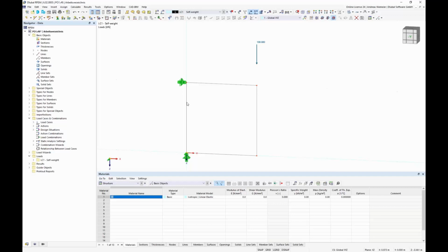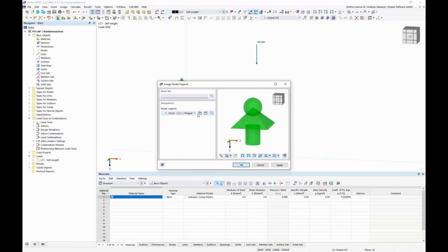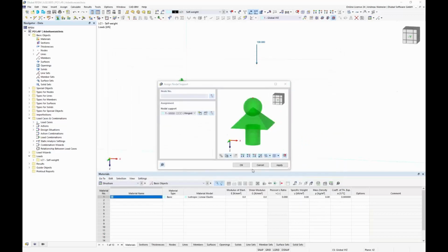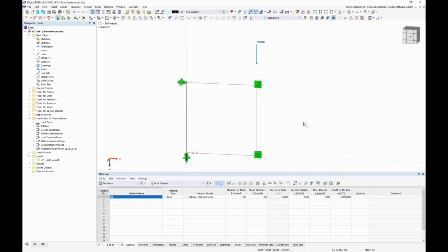And so that this structure cannot rotate around the global z-axis, I place also here 2 supports in y direction. So these are my boundary conditions and should show you my target place where I want to operate now. So if you see this load and you see these supports, our task is how we can carry this force down to these supports.